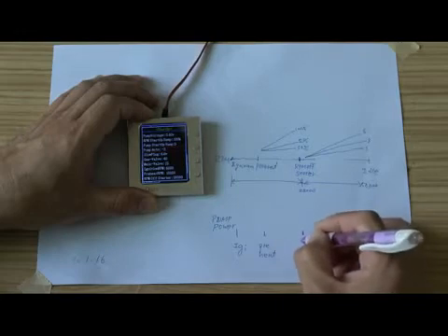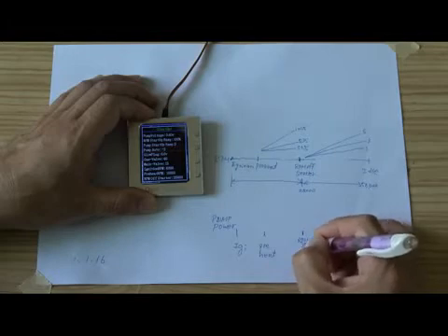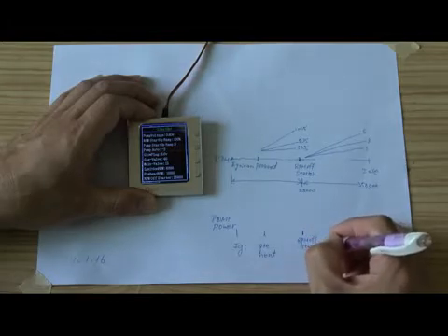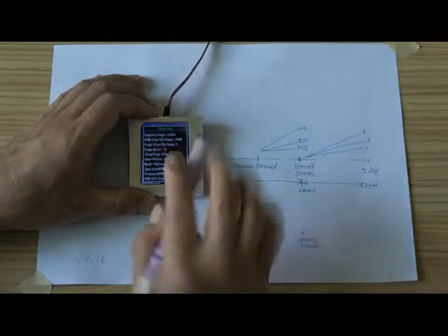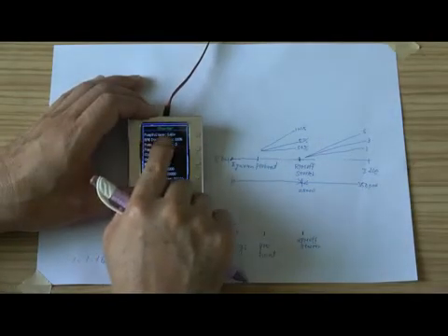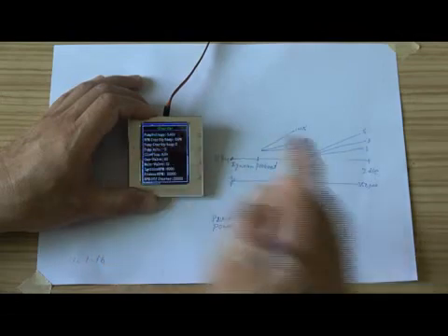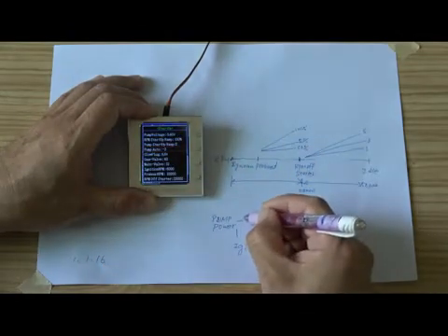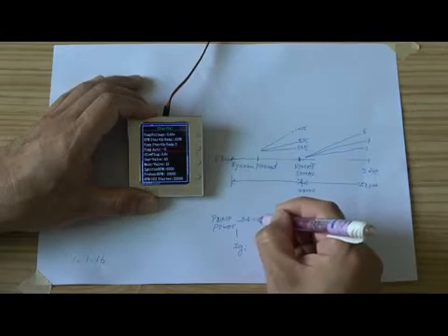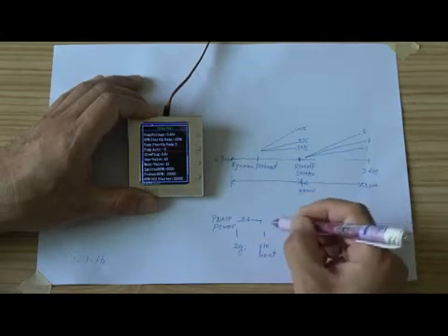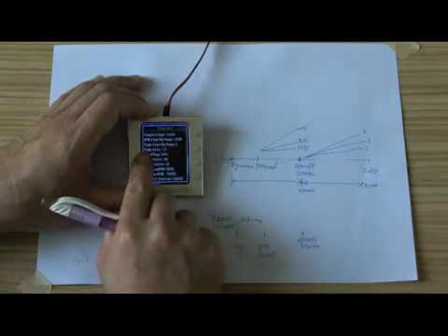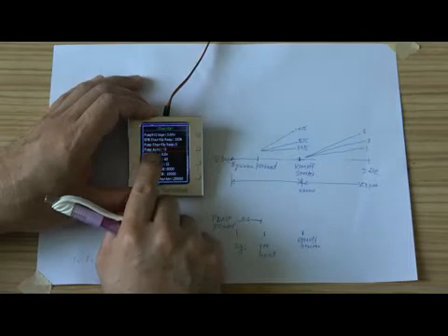This is the RPM of the starter. When ignition, the pump power is controlled by pump voltage, 0.4 during this time. When ignition is successful, the pump power will be controlled by pump auto.